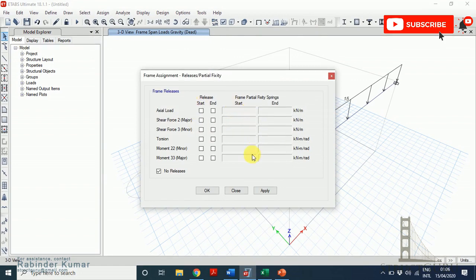You can see there are various check boxes in this dialog box which are for releasing or making a 100% pin connection. One is the start point of the section and the other is the end point of the section. When you click the start point, there will be a value which is by default 0, which means the stiffness is reduced to 0 and this creates a pin connection. So let's do it. First we will run the analysis with no release. No release means the connection is fixed. Let's do it and compare the values.